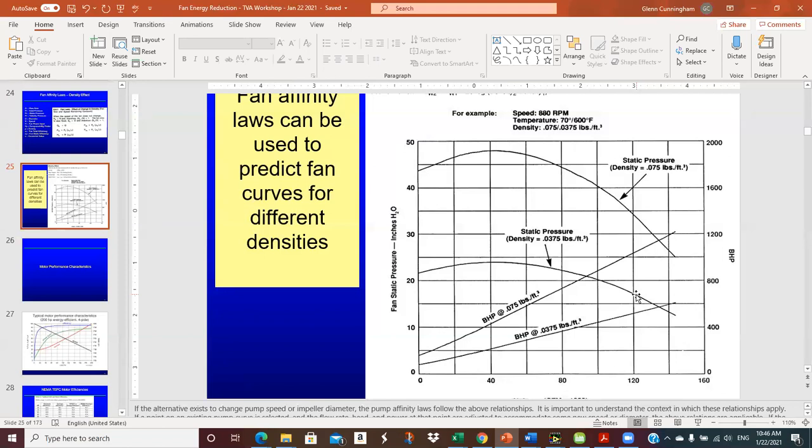Well, that's a really good question. So, what I would say is, one, VFDs do go down. If the VFD goes down and you have to bypass it, you're going to go back to 100% flow. And if you want to operate, you may need to have that damper there. Now, that damper is going to have a pressure drop. Even in the open position, it's got a pressure drop.